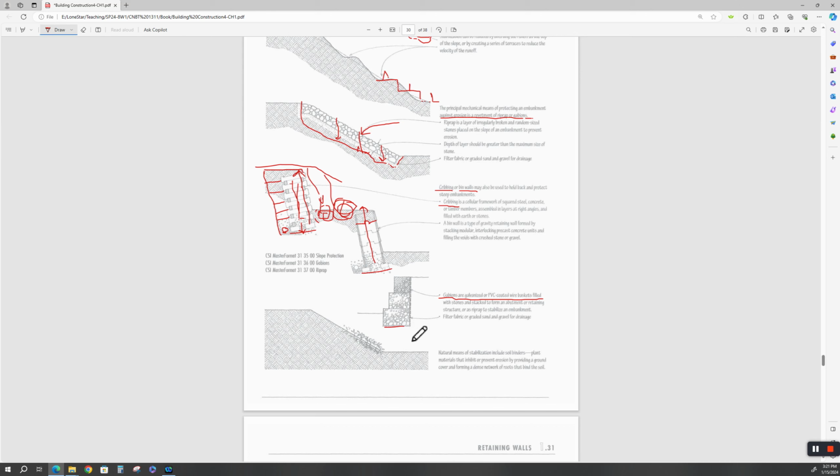Again, if you're going to do this for true erosion control, you need really a fabric, a geofabric, geotextile behind it. Okay, this is your soil over here. That way, the water, if it starts building up, can migrate through there and hydrate the soil. We use these over in the desert to protect against IEDs. They were big boxes, and we filled them full of sand. Those are gabions.